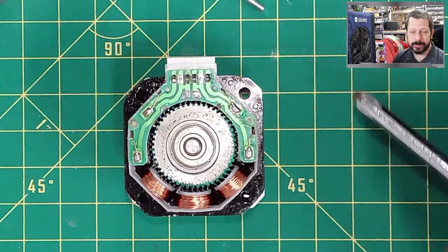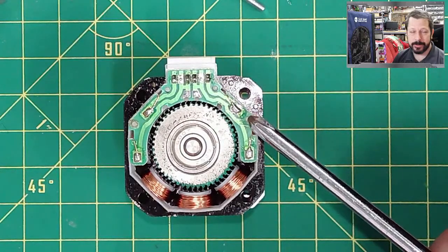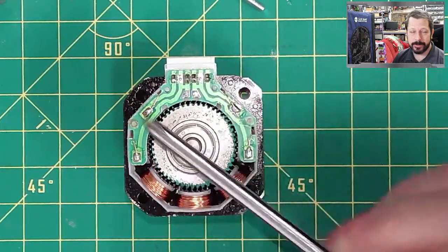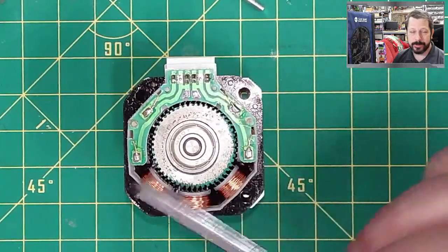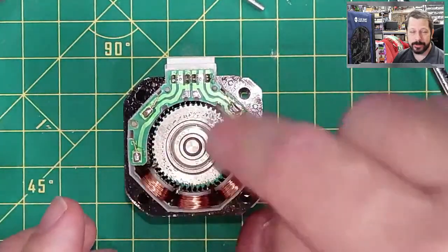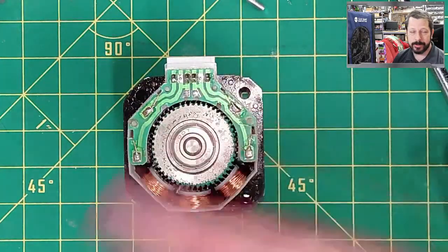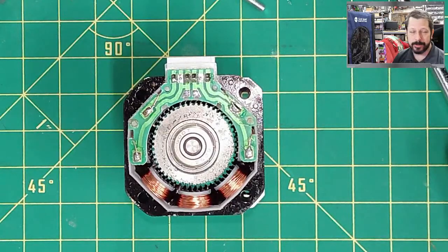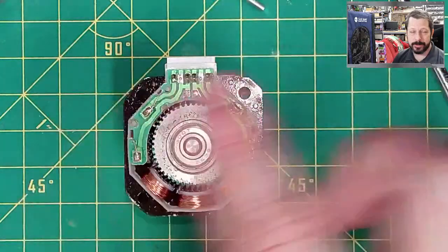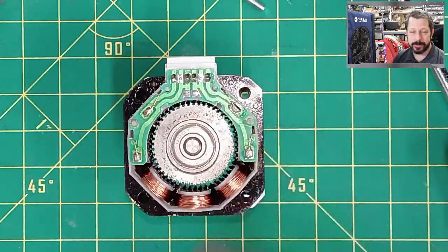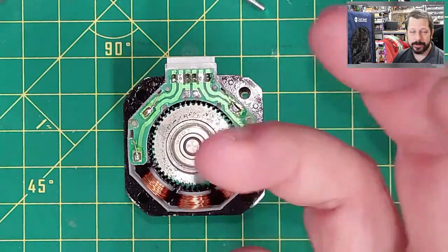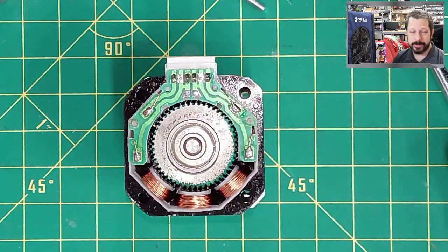So basically, what it does is it will energize pairs of coils, and inside the core here, which we'll take out in a second, there's a permanent magnet. So you have electromagnets on the outside that you can turn on and off, and permanent magnets on the inside, and the combination of which electromagnets are on causes the permanent magnet to be attracted or repelled from where it's currently at to go to a new location.